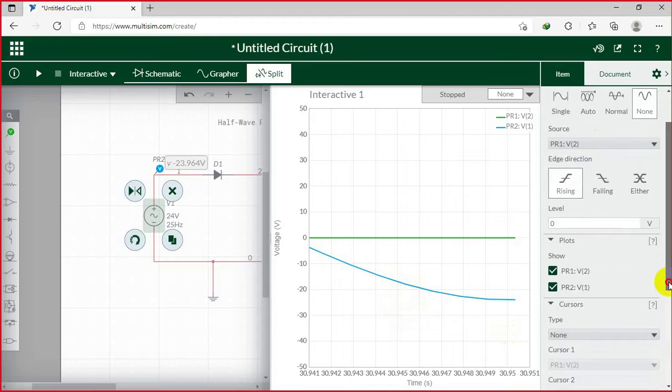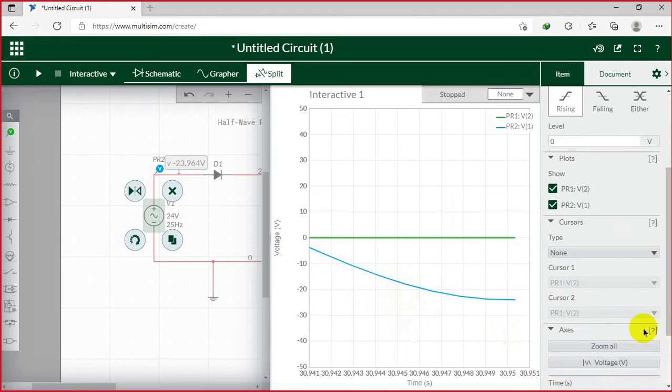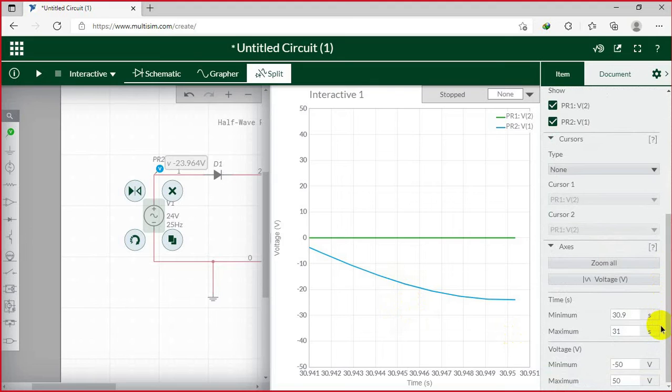And let's change the timing. I think then we'll see a better shape. Okay. We want to see the time on both sides. Okay, so what we can do is check the time per division, what division it is showing.